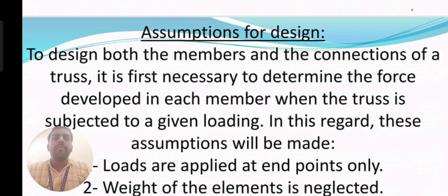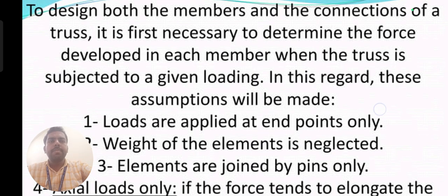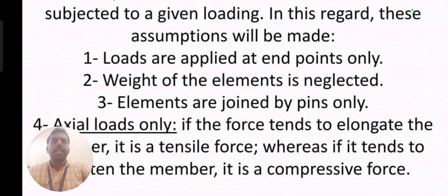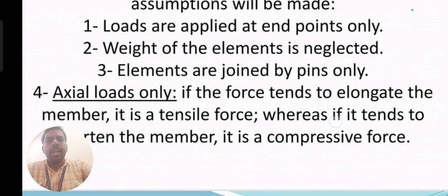It is necessary to determine the force developed on each member when the truss is subjected to a given loading. In this regard, these assumptions will be made. What do the assumptions mean? First of all, loads are applied at the endpoints only. The second one, the weight of the elements is neglected, and the third one, elements are joined by pins only.